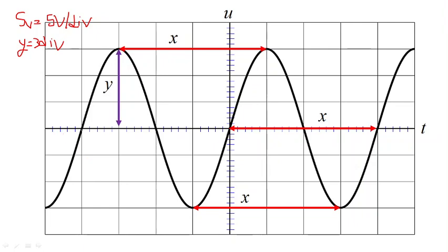For an oscillogram, the horizontal axis is for time, the vertical axis for voltage. An oscilloscope is a device used to display voltage as a function of time. X represents the number of horizontal divisions for one cycle, between 2 consecutive crests or 2 consecutive peaks, or from trough to trough. Similarly, SH is the time corresponding to one horizontal division.